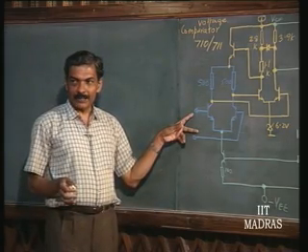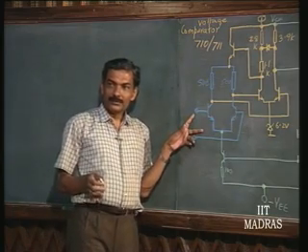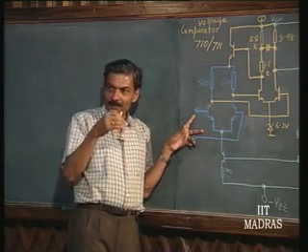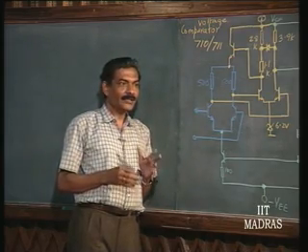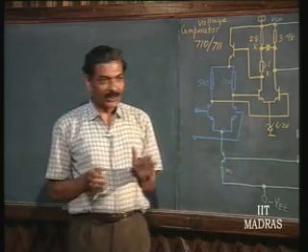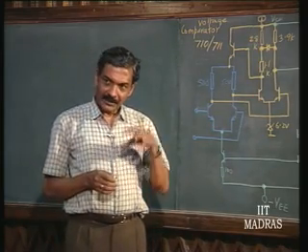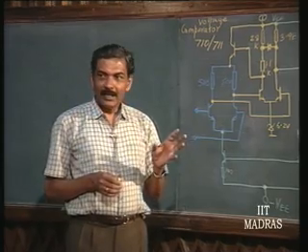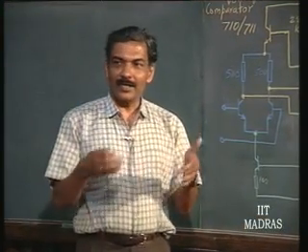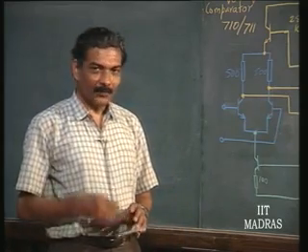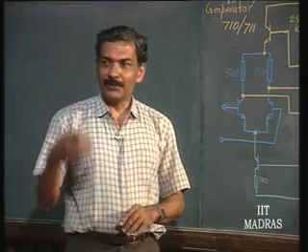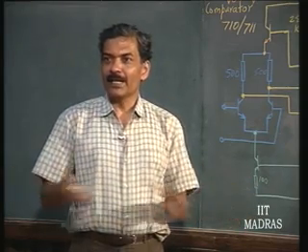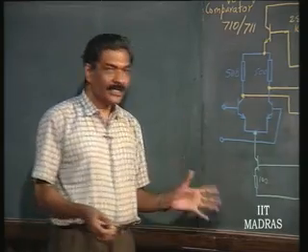Two voltages it is comparing, and even though the output is ultimately going to be in the high state or low state, it has to go from high to low or low to high, and this has to occur at the highest possible speed of operation. Now, we are not bothered about slew rate etc. for this. Slew rate is the characteristic of the structure when output is following input to a certain extent and the distortion starts happening, because now output can no longer rise at that rate. Whereas here, we are not bothered about the output input relationship at all. We want the output to reach high as quickly as possible, whether it is a linear relationship or a nonlinear relationship, we are not bothered about that. So, speed is what is important.